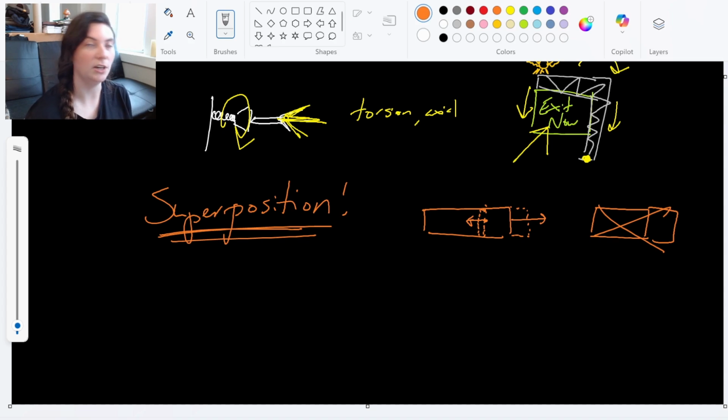But in the axial load video, we just said, hey, we can just add these displacements together. That's essentially the idea of superposition. I got two different things going on. To get the overall, I just add them together. And that's exactly what we're going to do with this combined loading. Right, so some of those equations that we've seen before are all going to come back now.